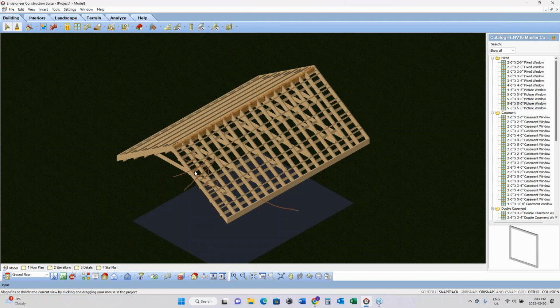You might still want to have the battens and the purlins for temporary bracing, or the collar ties and the rafter ties going in. You can turn on and off the different elements that you want, and you will still need that fascia board to attach to as well. So you can put all of those in, even though you're not rafter framing, you're truss framing. So those are how you get all of the different elements for rafter framing, and all of those will be included in your material list. Once they're turned on, they fully count and become part of that list as well.